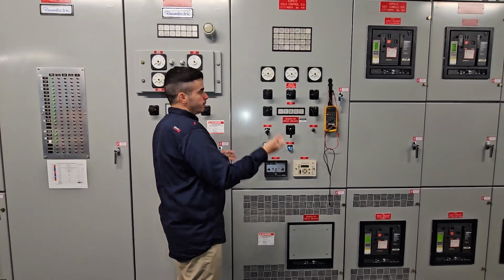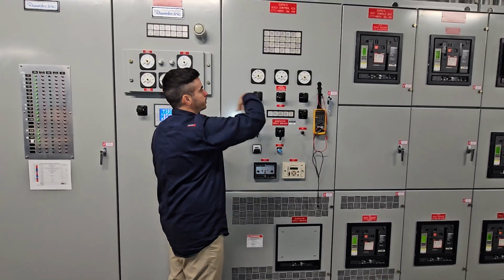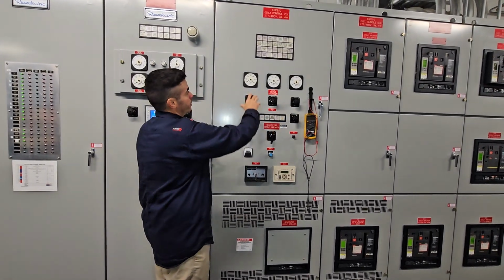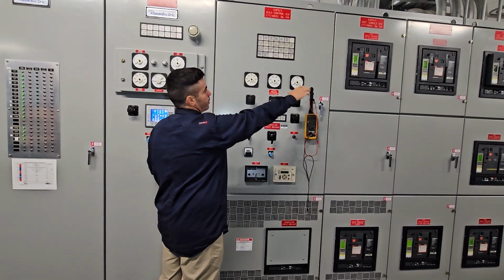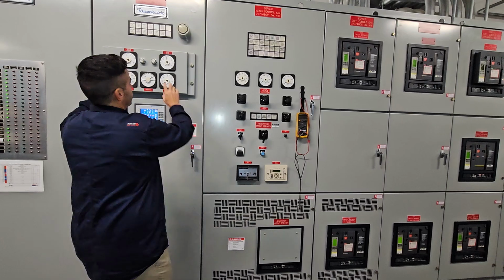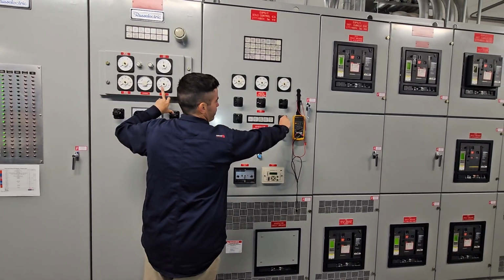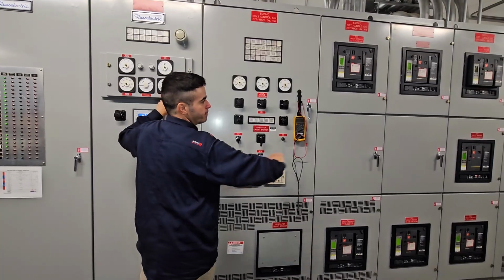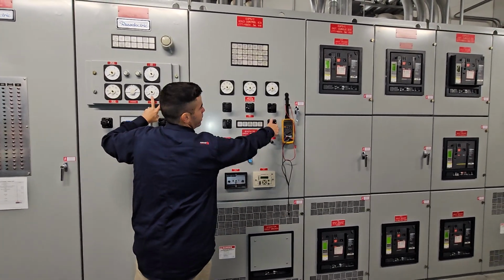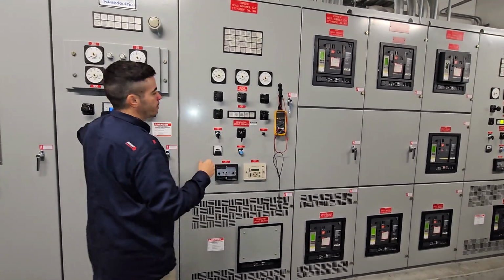Now, when you already have one and you're bringing the second one online, you're in the run position, the generator is already running, and the other gen is already connected. For this gen, I already have 480 and 60 hertz. I can check the frequency here. Remember, I told you we only have one meter. If I go to bus, I'm checking the frequency for the generator that is already connected. If I go to gen, I'm comparing the frequency with the generator that is incoming.